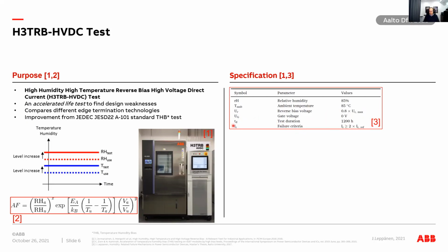And for the failure criteria, there are different means to do this. Some automotive standards state that it should be 5 times the reference leakage current, or in some cases we use 2 times. Typically ABB uses 2 times. It's just peanuts in my opinion. It can shift the failure statistics distribution a little bit, but really it doesn't matter what the limit is.